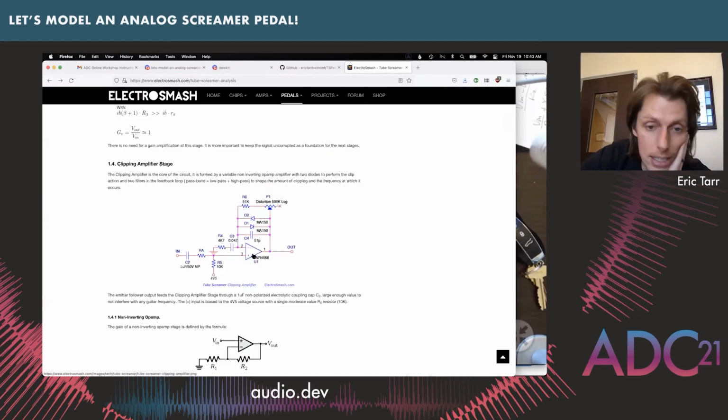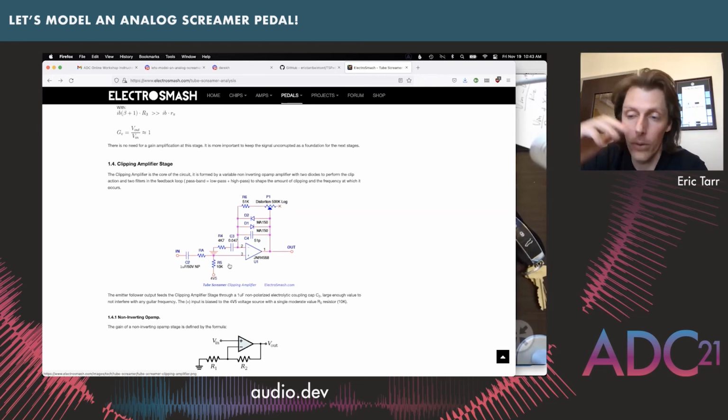Okay, so here is our circuit for it. One of the things that I'm going to do to simplify it for us is, again, we have this DC offset, and I'm going to ignore that and say we're not going to have any DC offset to worry about, or we're going to allow our signal to go positive and negative. And because of that, we have a voltage that's coming in, and we have these components that we encounter, some capacitor, some resistor here. If we just treat this circuit in isolation, there's no current that's allowed to be drawn to go into the op amp over here.